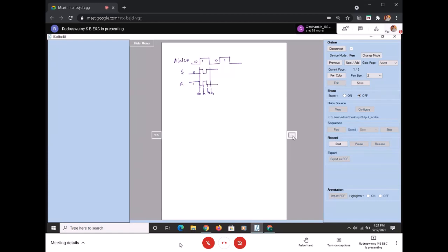If it is master slave and edge triggered, both are kind of the same. Now, if it is a positive edge trigger, meaning this, all of you agree? Only at the rising edge is this enabled. Only at this instant. Rest all is disabled. Only at the rising edge of my enable or the clock input, the flip-flop is enabled.